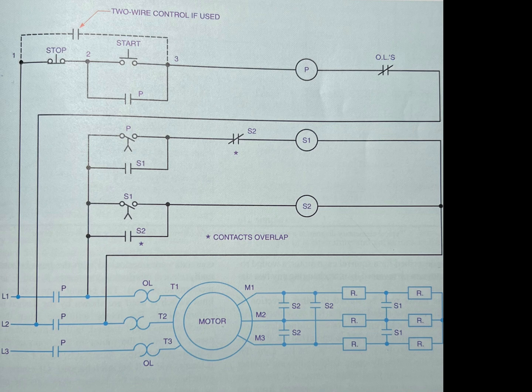The operation of the accelerating contactors is controlled by a timing device. This device provides time acceleration in a manner similar to the operation of primary resistor starters. Normally, the timing of the steps of acceleration is controlled by adjustable accelerating relays.